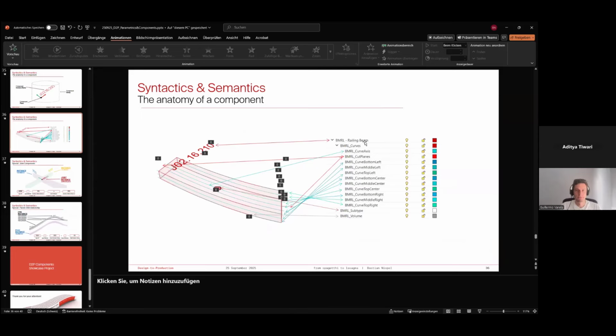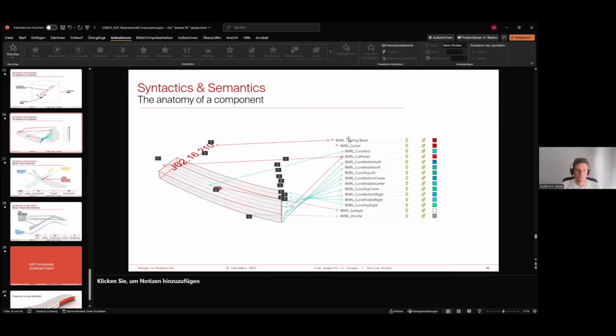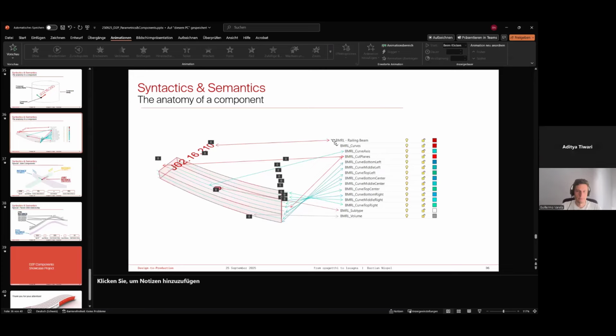So we have a railing beam, and that stands for BM, beam, RL, railing. You can do whatever you want to, but usually we do it capitalized, and it's about readability. You don't want to maybe introduce special characters though. So dollar signs or something like that could be messed up actually with regex. Besides that, there are no conventions, no.